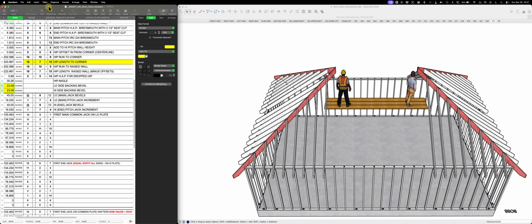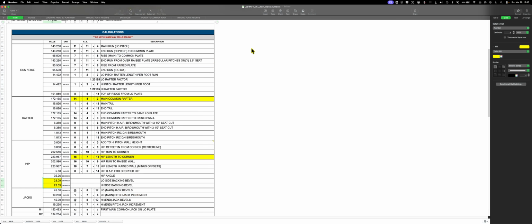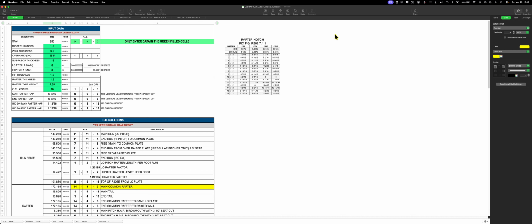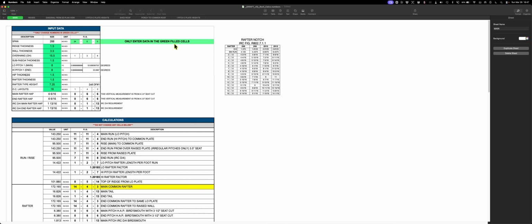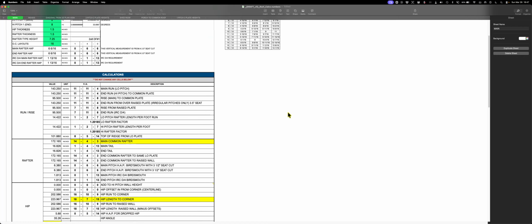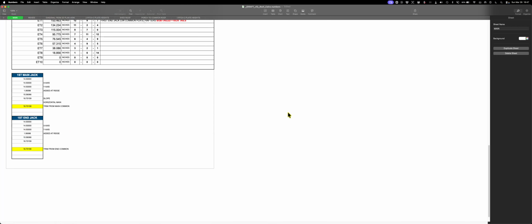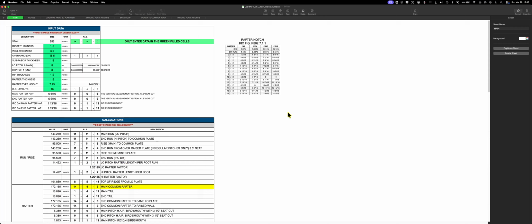And then let's go here. Or you can just use a spreadsheet. And yeah, this thing is worth its money. So I'll share the stair one for building stairs, because stairs are pretty simple. It's finished floor to finished floor divided by 7 5/8, and then whatever that new number is, round up to the next whole number and divide back through, and that'll get you your actual rise.